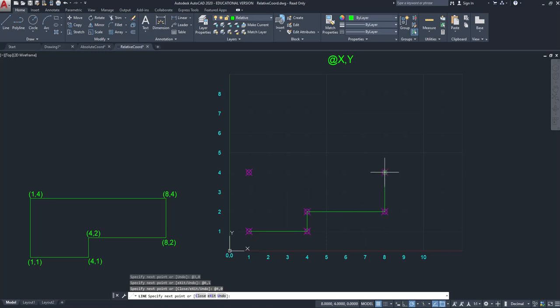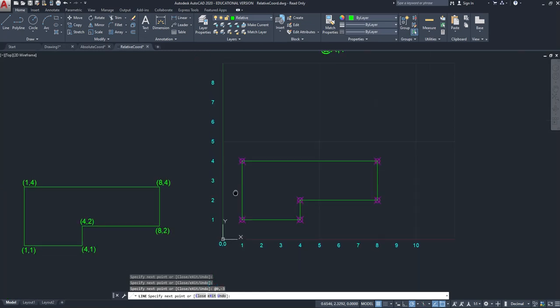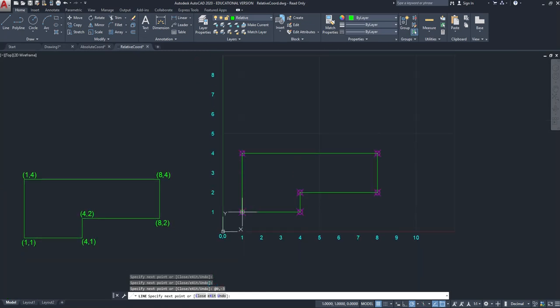Now, I'm going to cheat a little. Okay. Now we get to this point here. When you're creating an absolute input, there's two things that sort of affect it, right? So I can come over here and I can type at. So in the X direction, it's 0, comma. In the Y direction, this is negative 1, 2, 3, negative 3. Enter. Do you see that? Do you understand why that worked? Because in the Y coordinate, when I'm moving in the downward direction, it's negative. Okay? Now there's a couple of things that affect this.